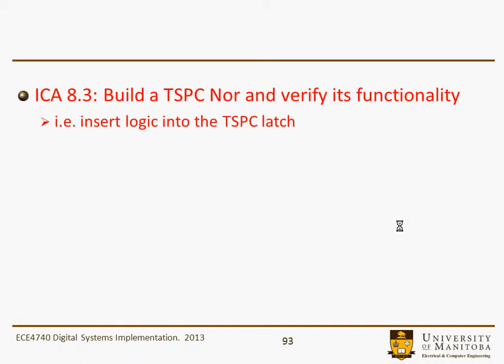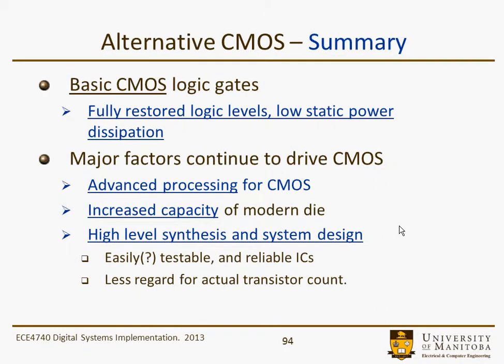So the in-class assignment here is to build a true single-phase clock NOR gate and verify its functionality. So basically you just insert some logic into the true single-phase clock latch. Just a little summary now.